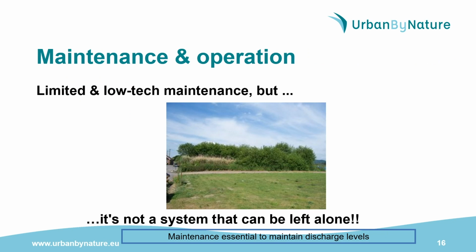Now I propose to move on to the maintenance and operation tasks of this type of treatment wetland. It's important to point out that even if natural treatment wetlands need low maintenance, it's not a system that can be left alone. Here on this picture you can see a treatment wetland without any maintenance for maybe several years, as trees are growing within the filter. Little chance here that the geomembrane is still effective.